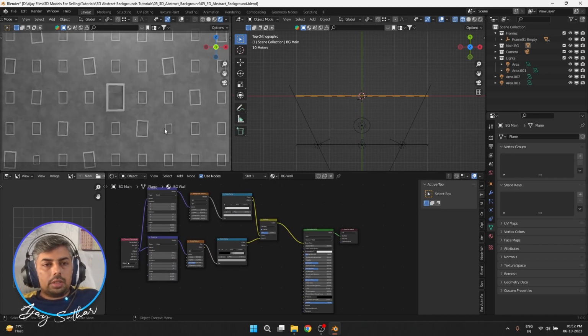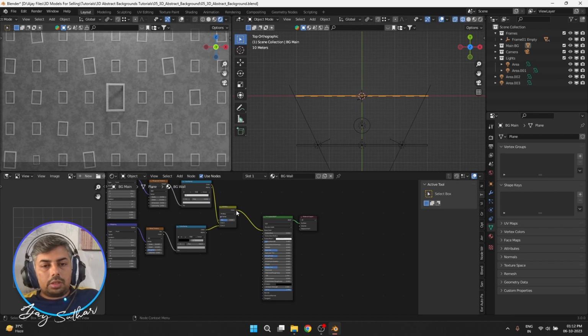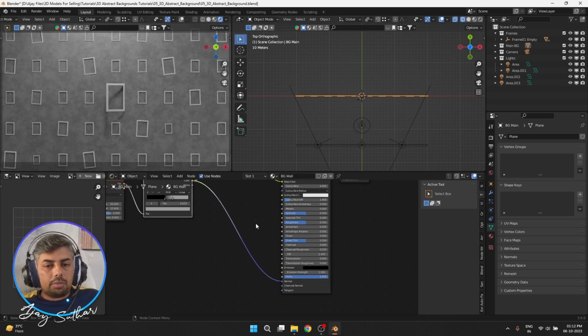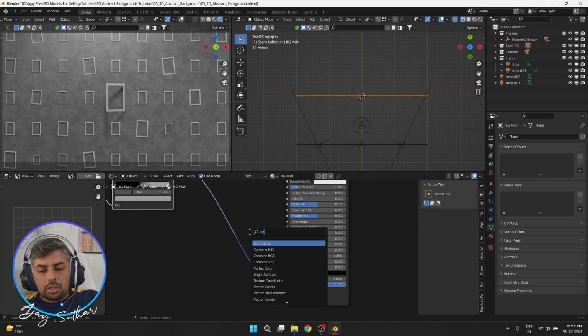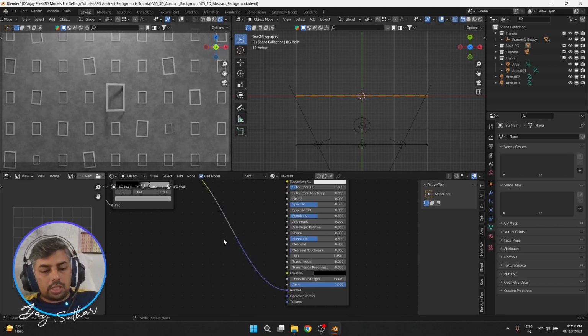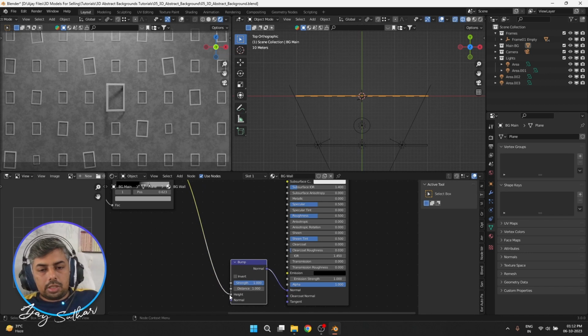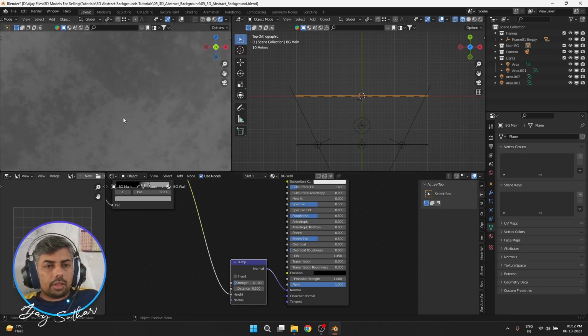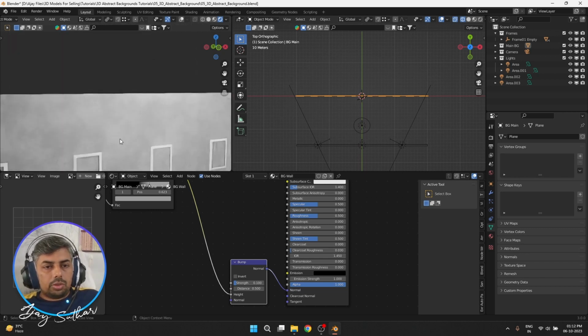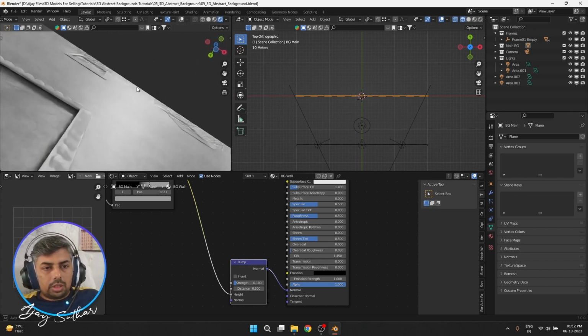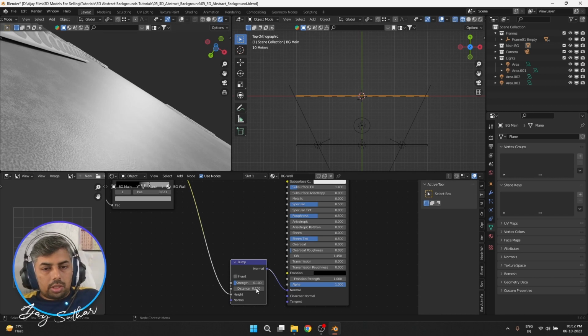And yeah, good. Okay, we also can create a rough texture. So normal, connect this color ramp to the normal of the Principled BSDF. Shift A, create a color ramp node, create a bump map node, connect it, get it to here, click to 0.1, click to 0.5. Let's see, you want to check, go zoom, you'll come to know.